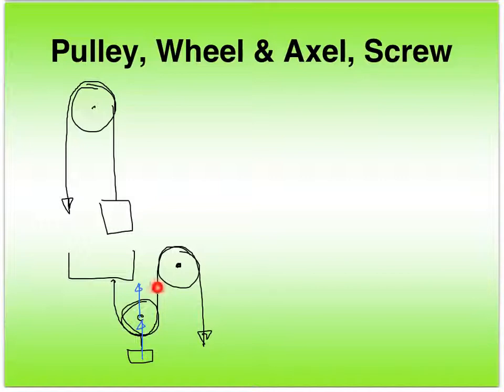But by doing so, I actually have two ropes here holding this one object up. It's kind of like you holding your weight up with two arms. Each one of these ropes now has 50% of the weight. This one's attached to a wall, this one's attached to another pulley. So as I pull this rope downward, this rope's going to work its way through, and I only have to use half the force that I would need to lift this object because I'm splitting it over two ropes, and I'm allowing this pulley to move.